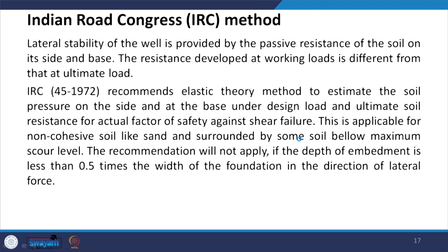So, there is a document of IRC, IRC 45 1972, and what has been recommended by this document is the elastic theory method. There are the ultimate theory method and the elastic theory method. We are going to talk today only about the elastic theory method to estimate the soil pressure on the side and the base under design load, and ultimate soil resistance for actual factor of safety against shear failure. So, you have 2 cases. One case is to estimate the soil pressure on the side and the base under design load.